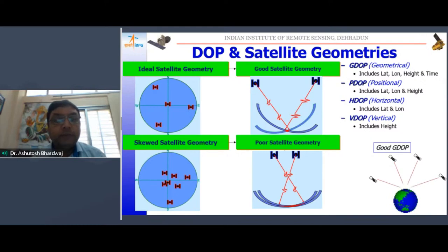But if you are using a multi-frequency receiver, because we now have GPS, GLONASS, BeiDou, Galileo, IRNSS, QZSS, these 6 systems are there roughly for our region. If I take the example of Dehradun, at our location we are very easily getting about 40 satellites at any moment in our GNSS receiver. 40. That is the kind of number of satellites we receive now, which is very good to provide us a very high accuracy.